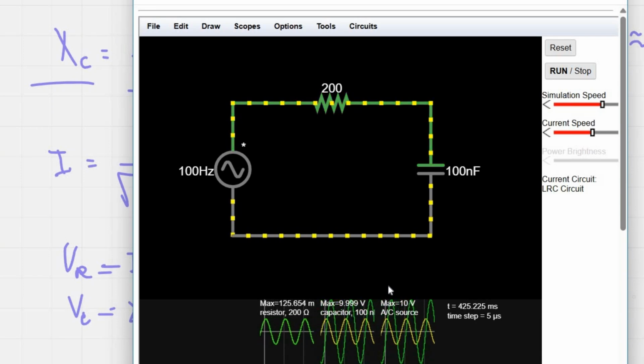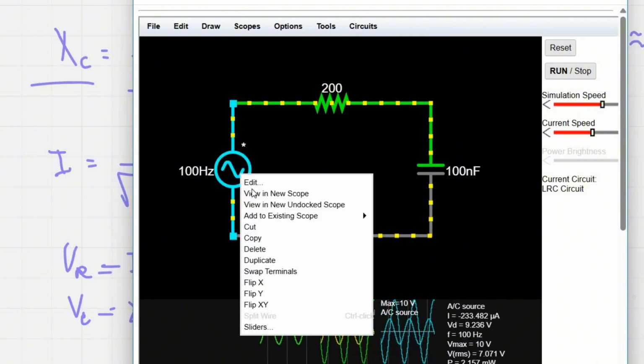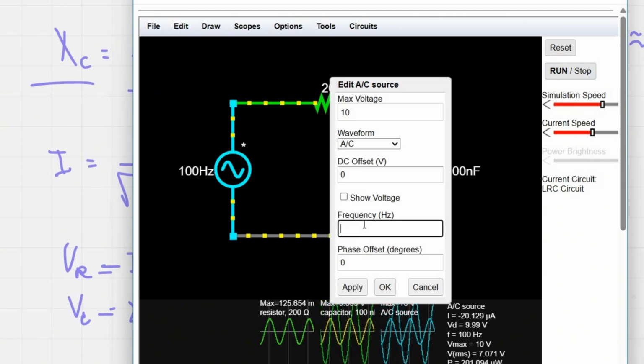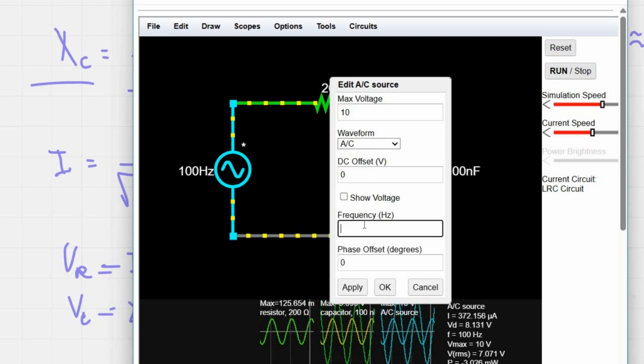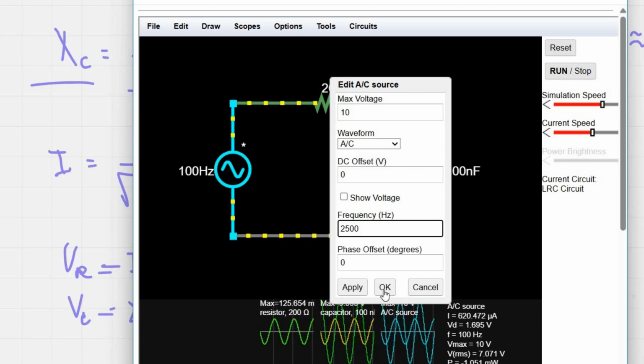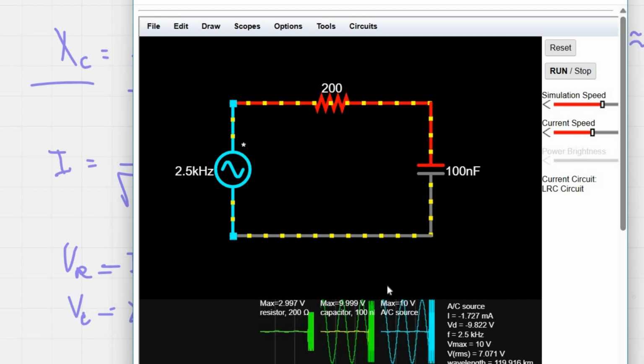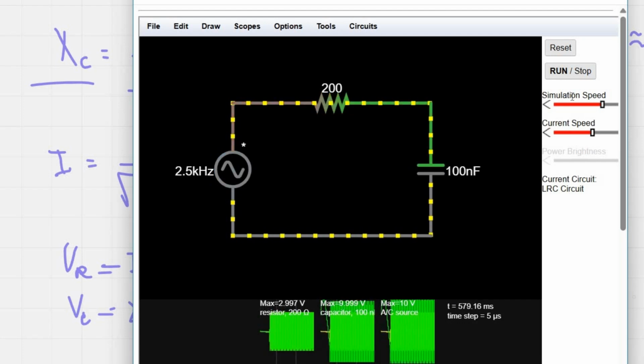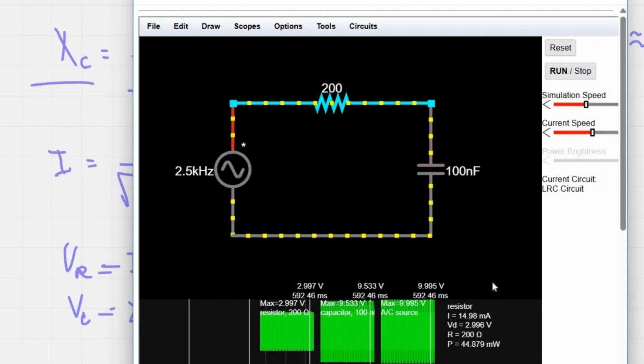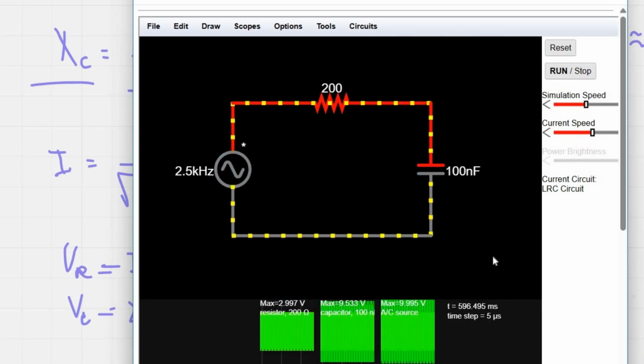So, a short conclusion for this. Now let me show the values given in the problem. Let me apply it. As you see, it's very fast. Maybe I will change the speed. But as you see, the graph looks like that. So the short conclusion for this problem: at low frequency, the capacitor dominates the circuit, and at high frequency, the resistor dominates.